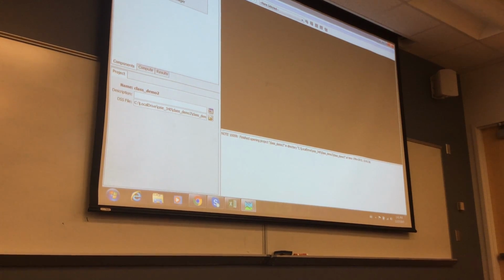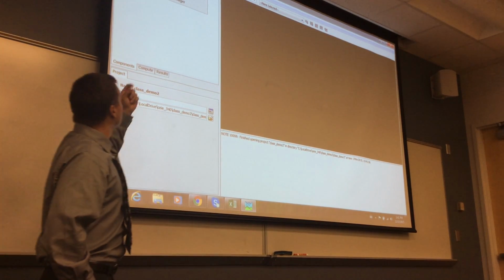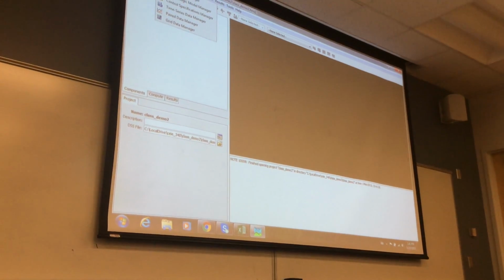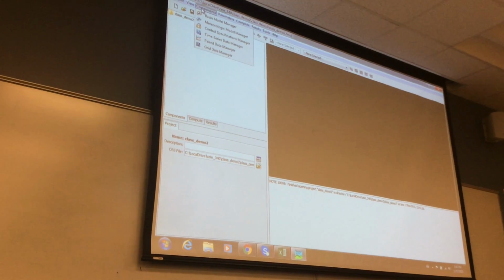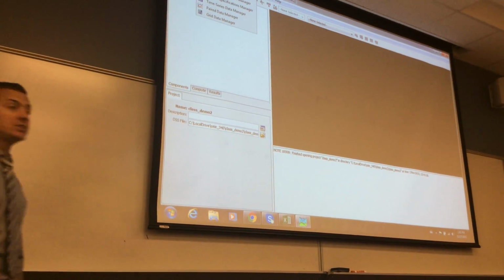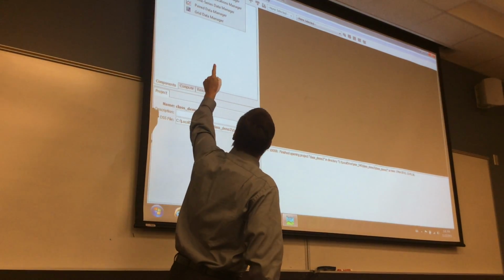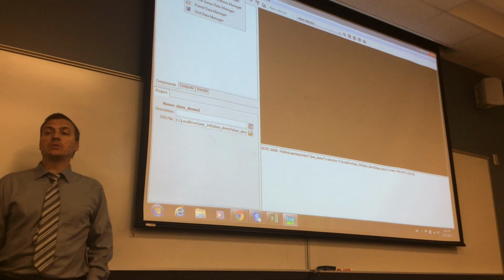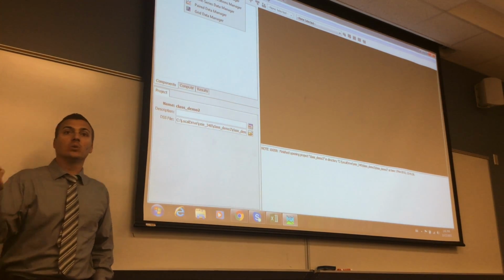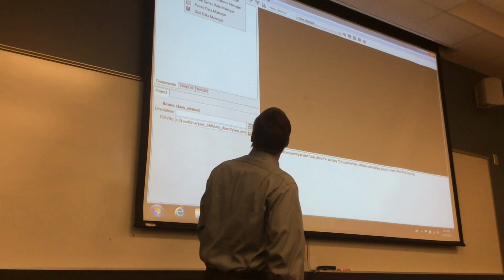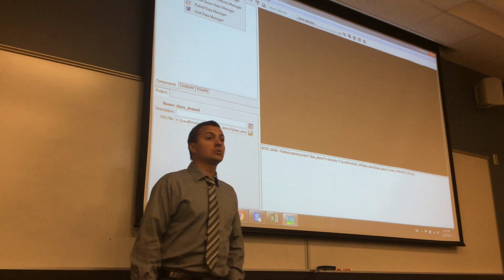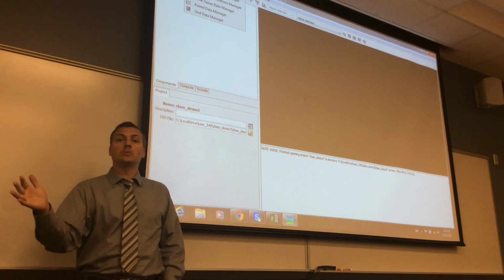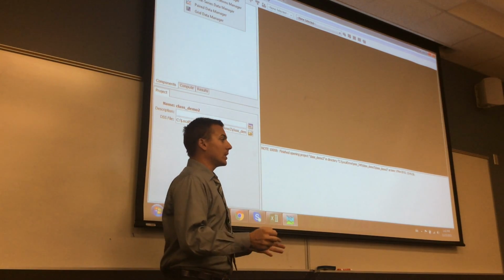So there are a bunch of components here. We will be using the basin model manager, which will create and represent the watershed. We will use a meteorological model, which will be forcing our model. We will use the time series data manager because we're working with time series for rainfall and river flow. And we will have a control specification manager, which will be used to set up a run, because we're running this model over time, so we need to put this run together.